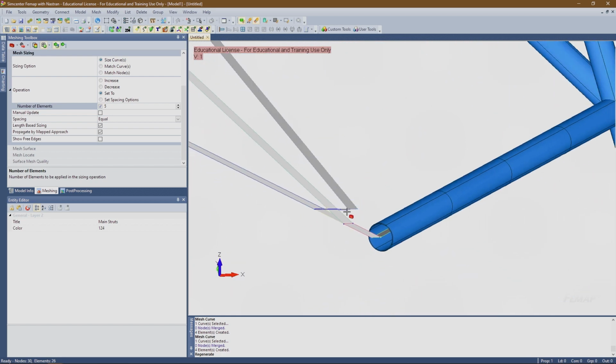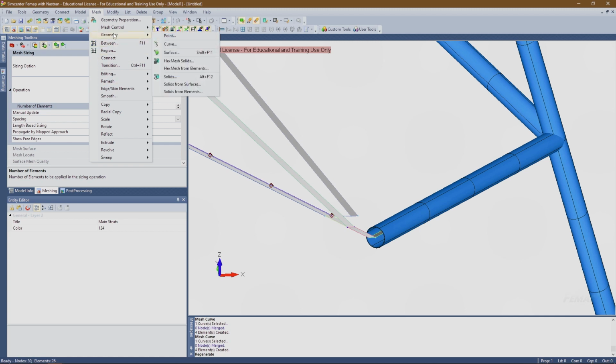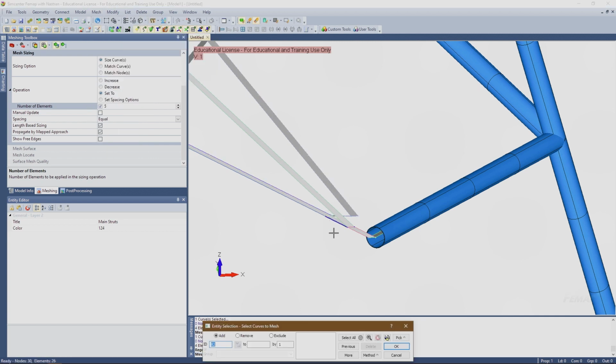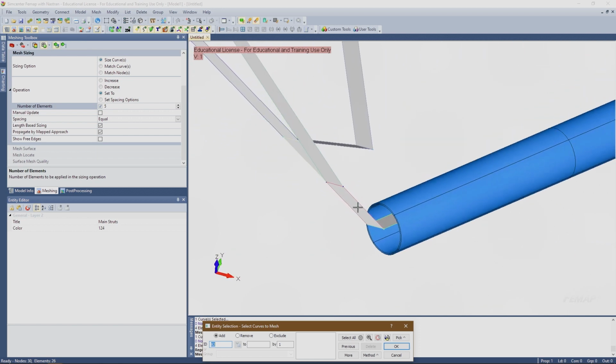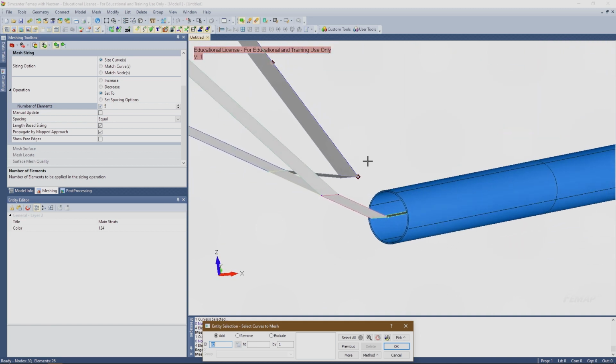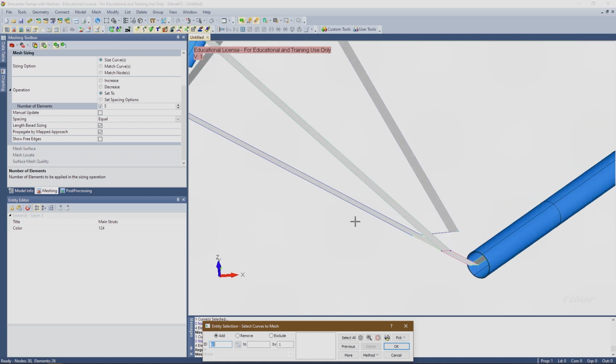Okay, great. So now we have to think about what we want connected. So we're going to go to mesh, geometry. Oh, and by the way, I will be changing property cards on these elements. I just like to get the mesh done and then think about properties later. So this whole thing is one big strut with like the triangle and the fork.